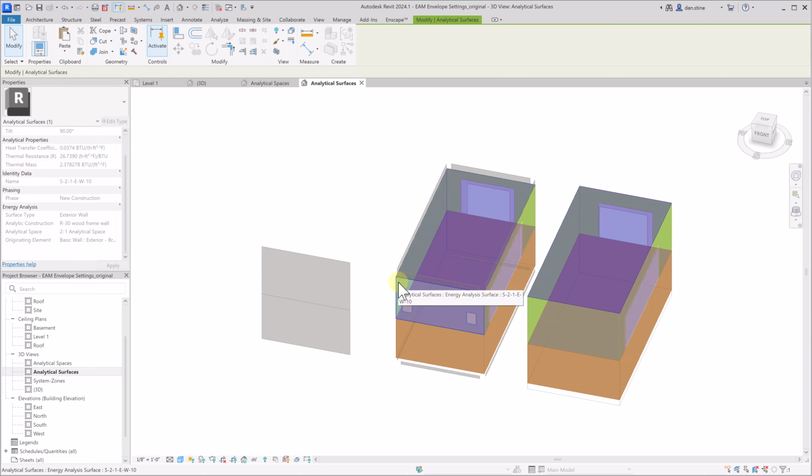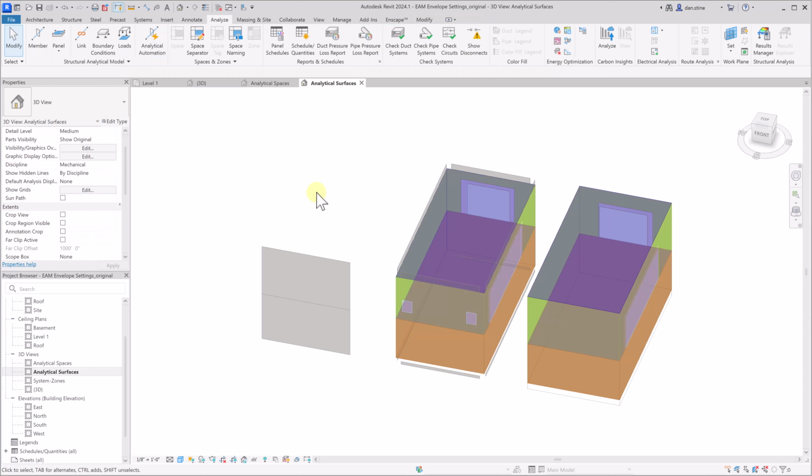And then if we select a wall, you can see that the R value is R26. And so it's not R30 because this is actually a wood stud wall, and there's going to be thermal bridging based on the studs. So this is a properly derated R value, which is really great. And so that's already showing the hierarchy. Now that we have an override for exterior walls, all exterior walls are going to get that selected option.